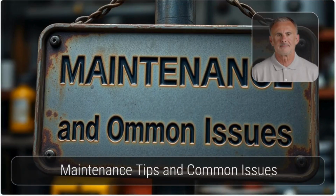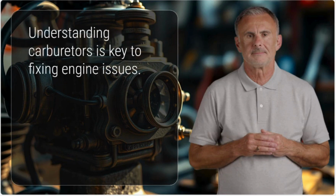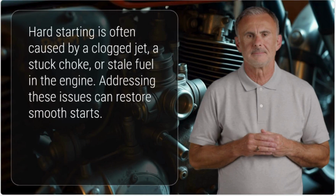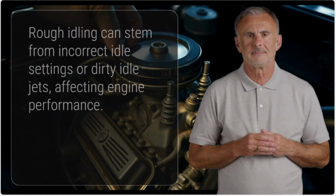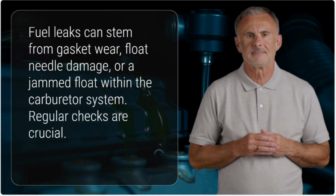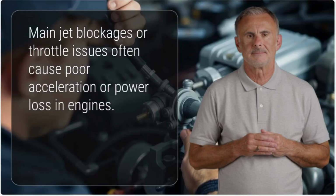Maintenance tips and common issues. Understanding how a carburetor works is essential for diagnosing and fixing common engine problems, such as hard starting, often caused by a clogged jet, stuck choke, or stale fuel. Rough idling or stalling may result from improper idle settings or dirty idle jets. Fuel leaks can be due to worn gaskets, damaged float needles, or a stuck float. Poor acceleration or power loss is usually tied to blockages in the main jet or improper throttle operation.